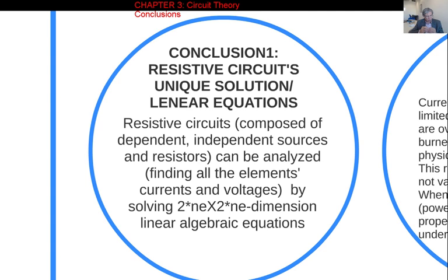How am I going to write these equations? I am going to write 2n equations. Independent ones are going to be mesh Kirchhoff voltage law equations, and drop one of the nodes and write for the other nodes Kirchhoff current law equations, and write the definition relations. All these equations, total number is 2n, unknowns 2n, then there is a unique solution. So these algebraic equations are the mathematical model of the given circuit.